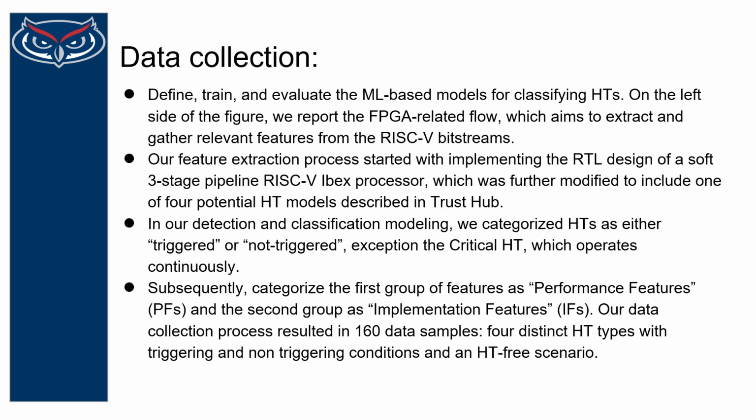Data collection. In this data collection, we define, train, and evaluate the ML-based models for classifying the HTs. On the left side of the figure, we report the FPGA related flow, which aims to extract and gather relevant features from the RISC-V bitstream. Our feature extraction process started with implementing the RTL design of a soft three-stage pipeline RISC-V Ibex processor, which was further modified to include one of our four potential HT models described in Trust Hub.